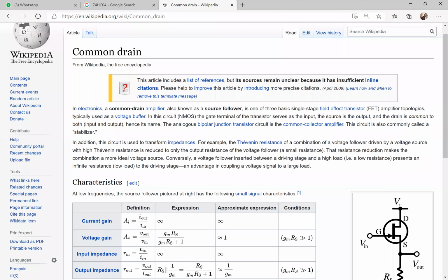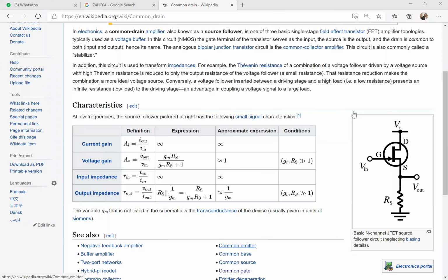So as you can see, even in the books, this is just used for current gain, and if you see the voltage gain, generally it is 1. So we have reached 0.6. That's close enough. The maximum you can reach is 1, because that's what it's being used for. Generally, it's more for current gain. It more or less looks like the current mirror circuit only. So this is what you can achieve from a common drain amplifier. That's why it is also called a source follower.